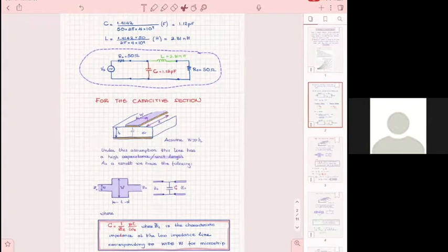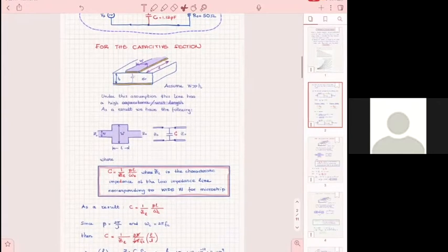So stepped means lines. If I tell you the lowest impedance you can use and the highest, that implies that's how low you can go and that's how high you can go. For a stepped impedance filter, you use the lowest characteristic impedance you can to realize the capacitor, and you use the highest impedance you can to realize the inductor.